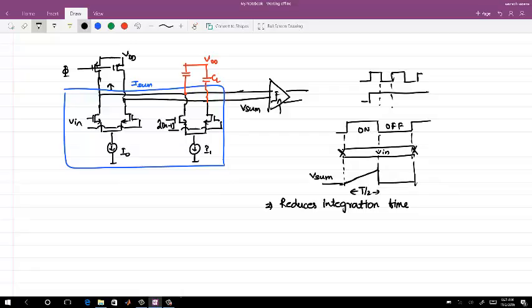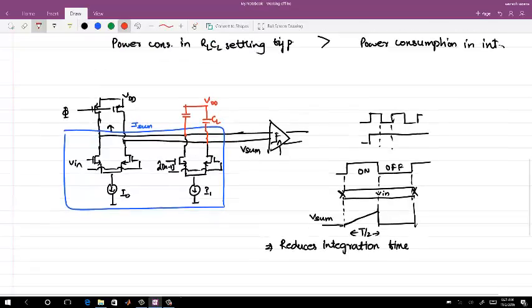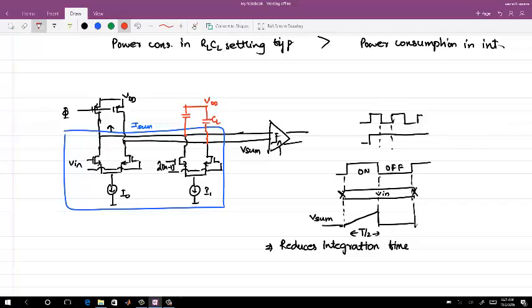Right. Now, if you say the reset period is not half of the time, then you have to generate that small reset. That's a pretty valid thing. So in place of this as a bit period, let's say this is the clock, I can have something like this as a clock, right? There's nothing which denies me from doing that. But now let me ask you the question. You are doing this at 20 Gbps. At 20 Gbps, you have 50 picoseconds. Normally you have 25 picoseconds, but you want to reduce it, let's say to 10 picoseconds.